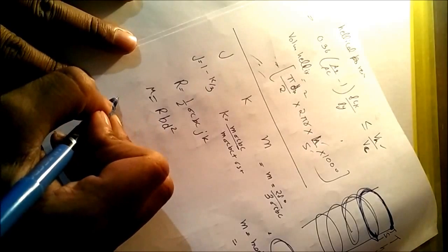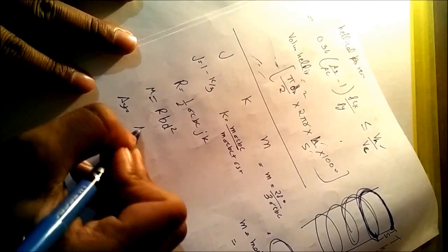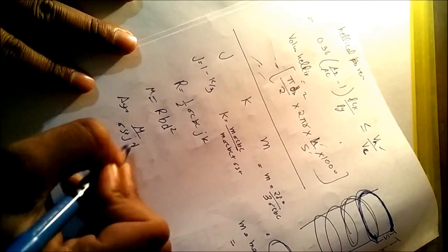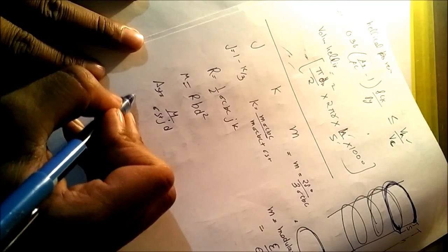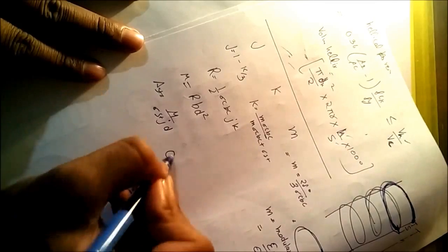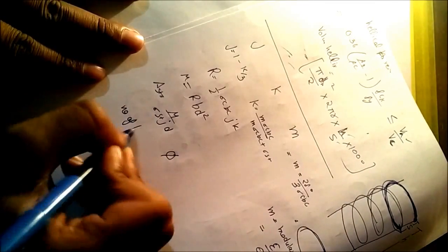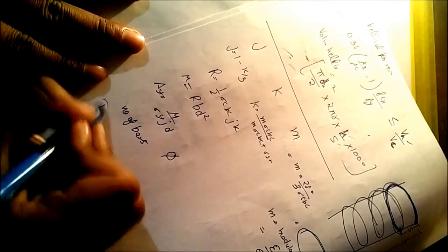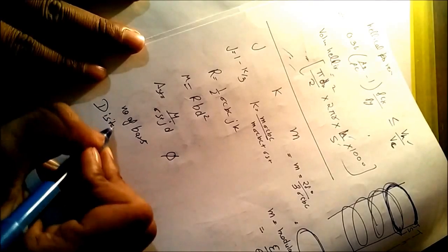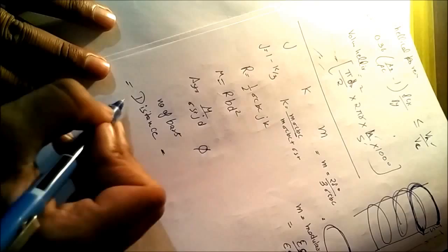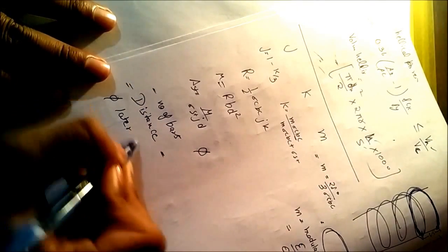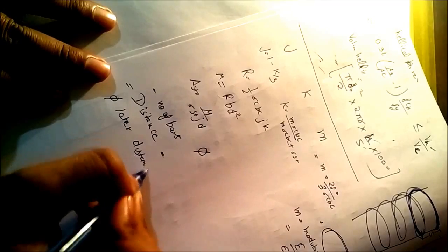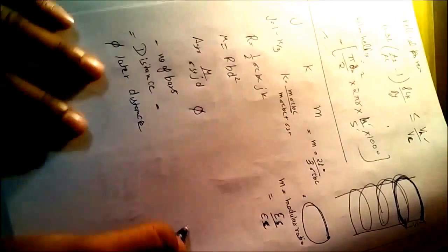Then area of steel AST is M upon sigma ST J D. From here, by assuming the bar diameter, we can find out the number of bars and then their distance. Remember the same for the lateral bars, we can assume 5 and the distance between them.